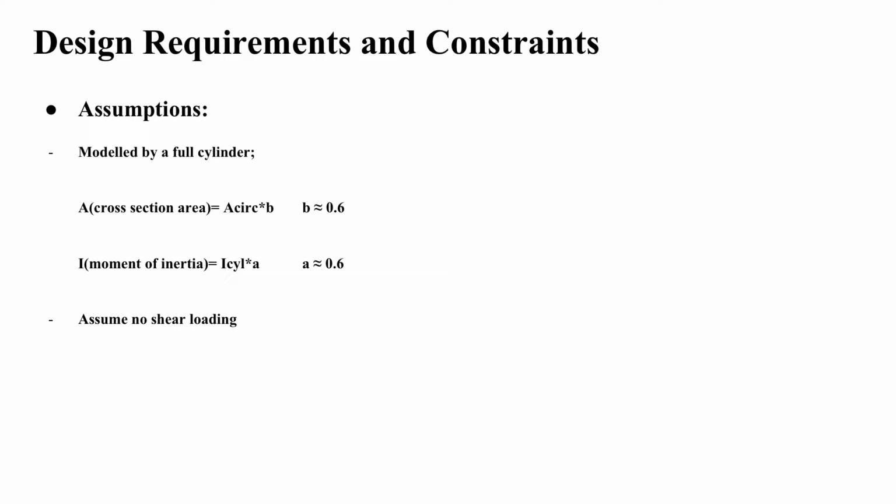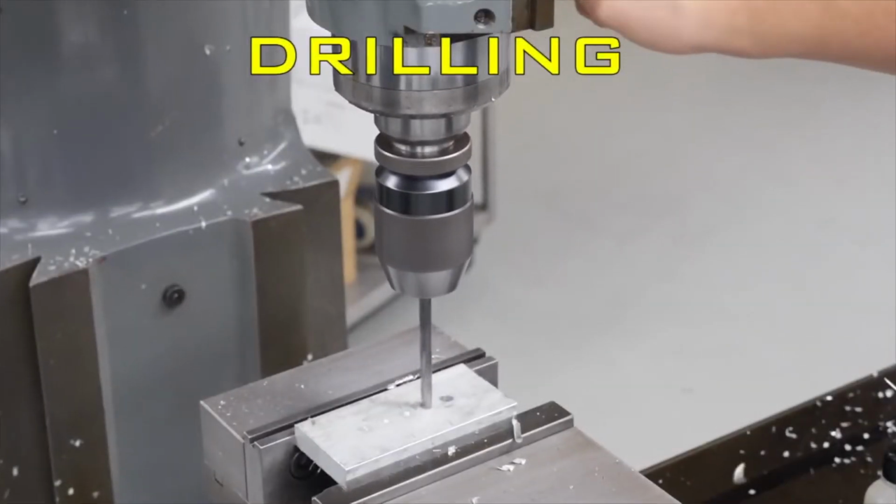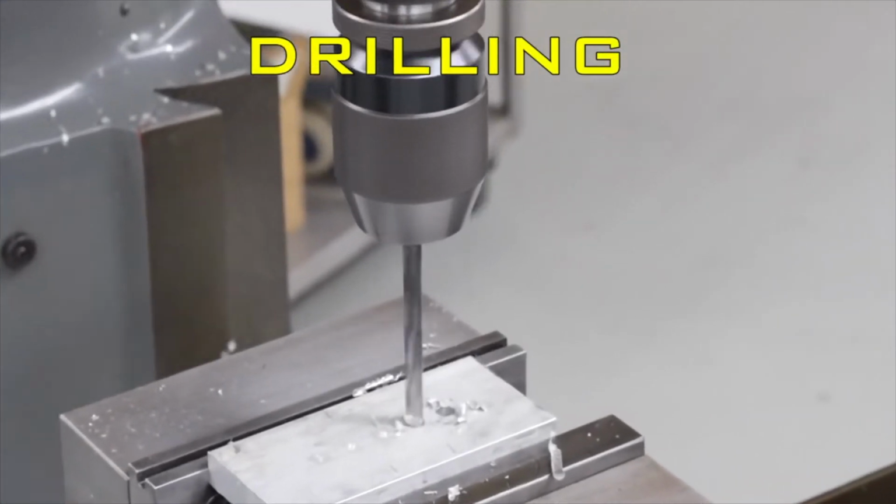The other assumption is that there is no shear loading on the drill bit. There is no force acting perpendicular to the axis. The assumption is valid for the defined situation, but may not be representative of real-world applications. Even though it is recommended to drill straight perpendicular to the material, in reality the drill bit may slip or walk, causing shear force and bending moment in the drill bit.